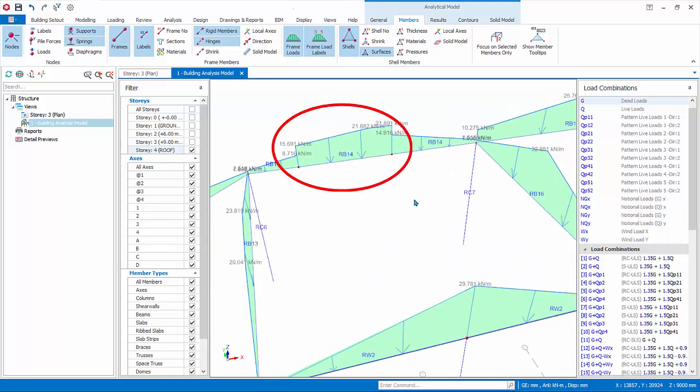As you can see for this perimeter beam, RB10, there is an abrupt jump in loadings. This is due to a partial cantilever slab supported by this beam. If slabs are included in the meshed building analysis, you should check the shell pressure values applied. You should go through each load case in detail.